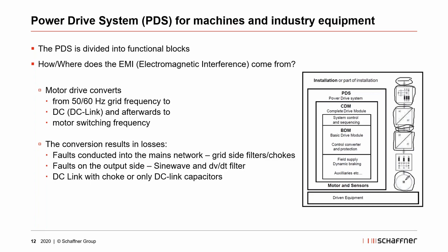With new approaches like SiC or GaN semiconductors, it's even higher than 15 kilohertz, or around 100 kilohertz. So it's really high frequency, and this switching causes losses, which should be clear to all of us. And this is why we need EMI filters if we want to connect to the grid.